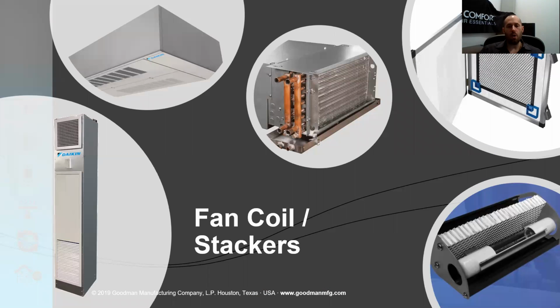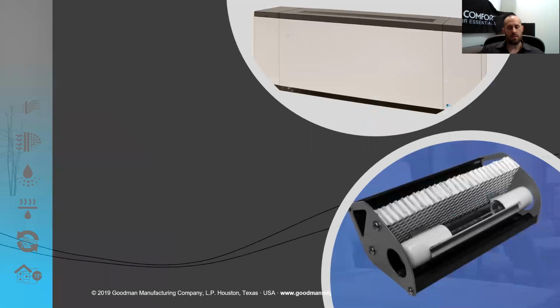When you're dealing with smaller fan coils, stacker units, or pancake coils, in these you have very limited space, so your choices are pretty limited. You can use small UV lights. You can use the small PTAC style air purifier. Maybe you can use a hybrid 1-inch electronic air cleaner. And sometimes we've seen where you can use a return air grill filter, but you're pretty limited with the amount of space you have.